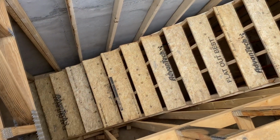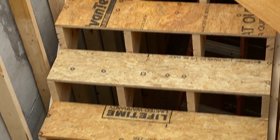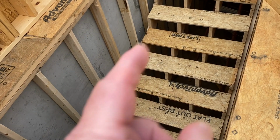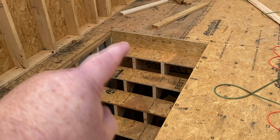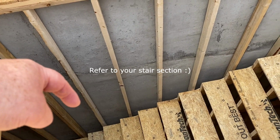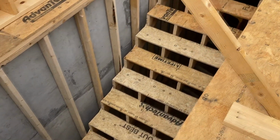Now you see those have Advantech on them, and that's permanent. Very safe construction stairs, and they'll make your treads a lot stronger. Most carpenters will just nail the tread right down to the stringer. But if you will allow for it, just lower your stringer 3/4 and cut another 3/4 off the bottom, like I was showing you in the drawing. Then you'll have very strong steps. And we always use 4 stringers.